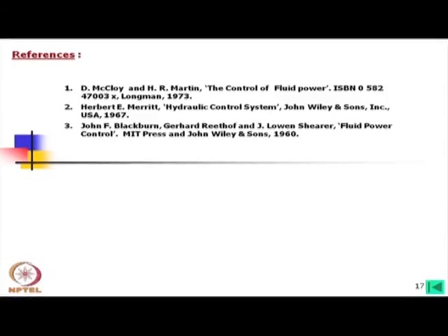For better knowledge you can also follow Martin and McCloy, particularly where the orifice sizes are discussed in detail, and in general terms, if you want more idea about the valves and their applications, you can follow the Blackburn book also. However, mostly I have consulted Merritt's book, Hydraulic Control Systems.